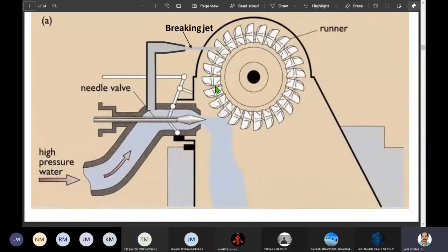So if you want to stop the turbine from operation, this is a heavy wheel, and even after reducing the flow rate to 0, the turbine wheel keeps on running because of very high inertia. It's a heavy wheel because the weight is fitted on the periphery. So the more weight concentration is towards the periphery.